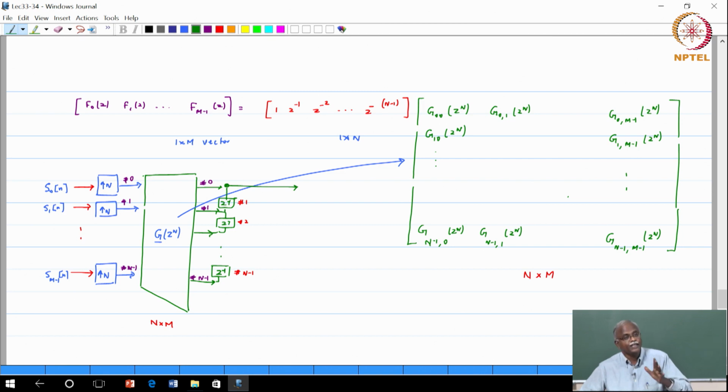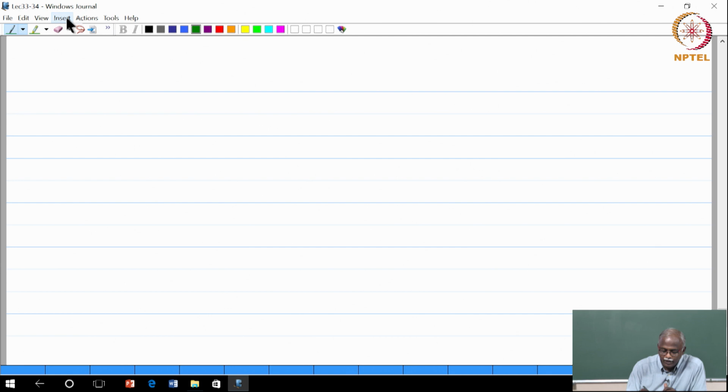We have not yet built the full system, we have only built the transmit portion of it, where we said that we are going to do upsampling by a factor of n, we are going to introduce some redundancy, and then we are going to see if we can exploit it in a way that is advantageous to us. Okay. Now, very important question, can I apply the Noble identity here? If every entry of your matrix is a function of z to the n, yes, of course I can apply it, which is the case. So, if I apply the Noble identity, what is the structure that I get?